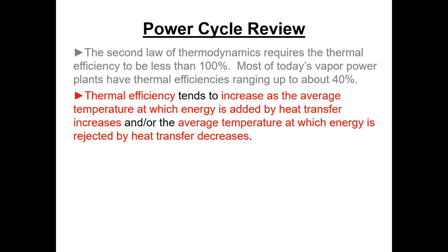And guess what? Kingston's a little more efficient in the wintertime because the temperature in the boiler is probably not changing, and the temperature of the lake, which is the temperature at which we're rejecting heat, is colder. And so we can have a little bit lower back pressure on the turbine, and so we can make a little bit more power.